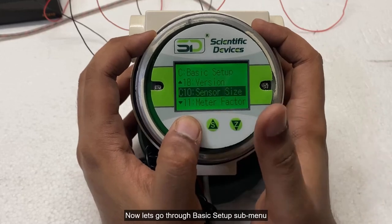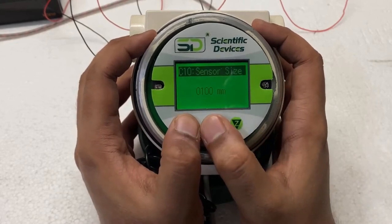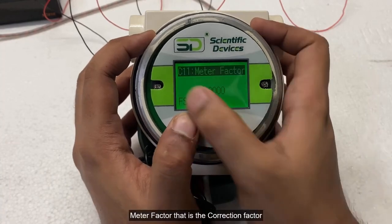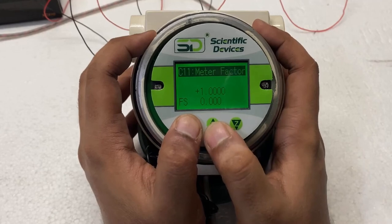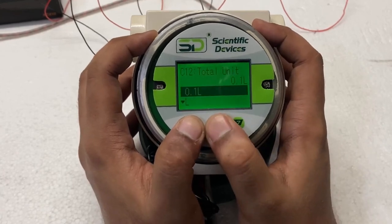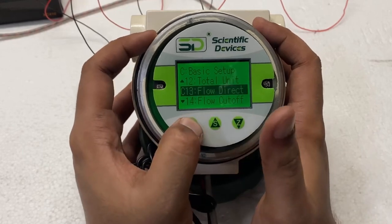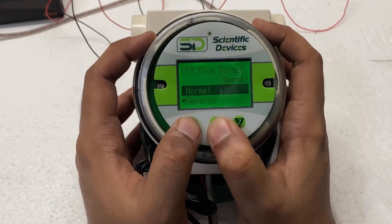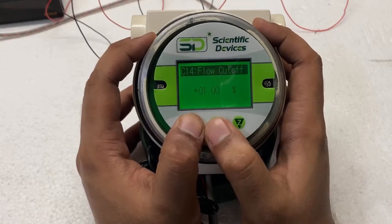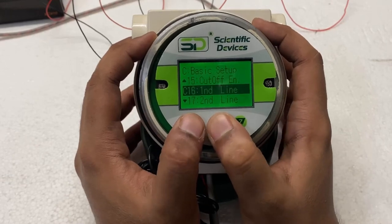Now let's go through basic setup submenu. Here you can set sensor size, meter factor, that is the correction factor, totalizer unit, flow direction, flow cutoff, first line to display.